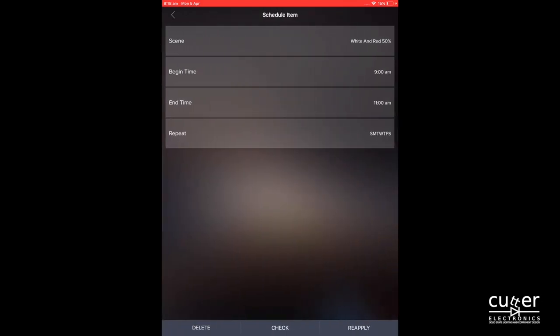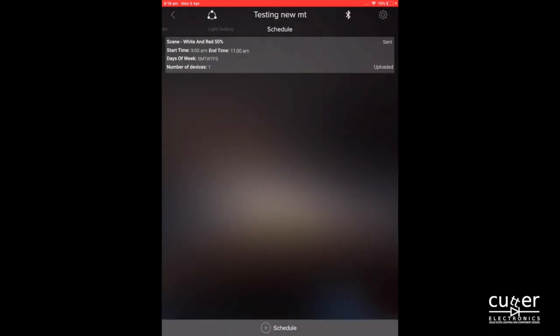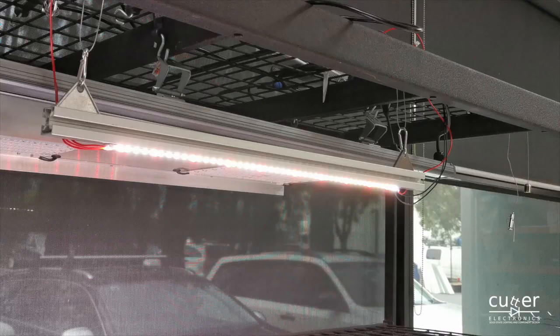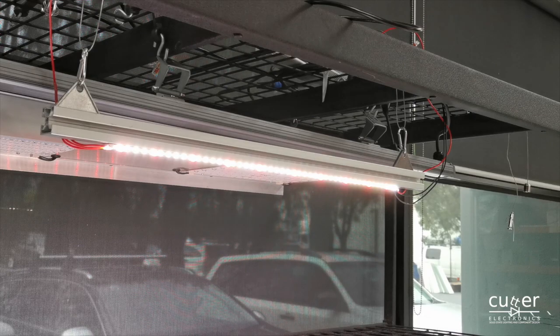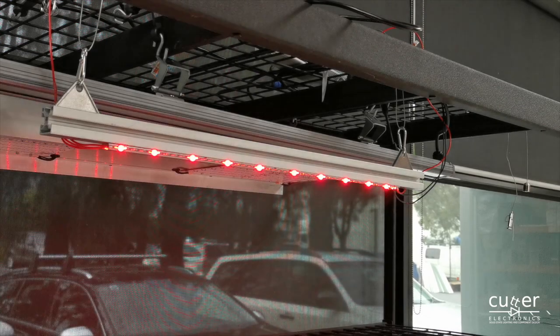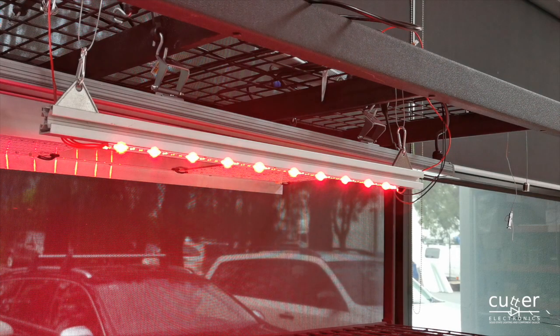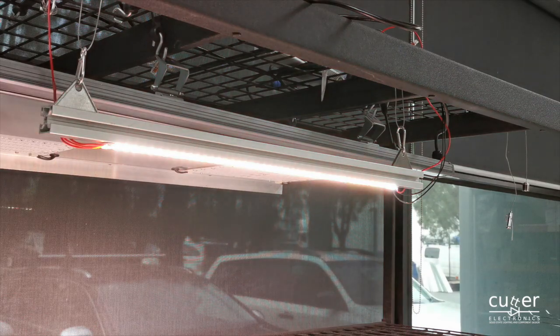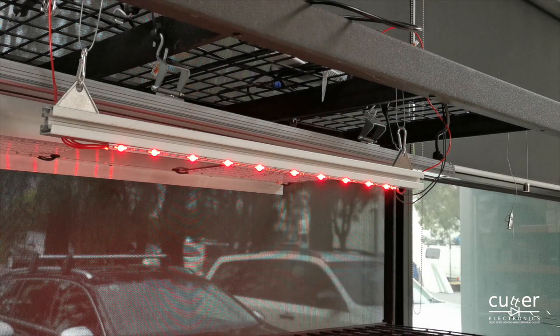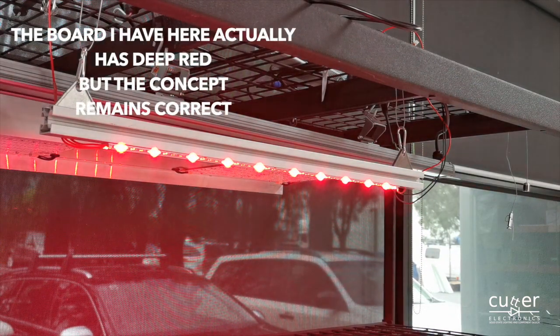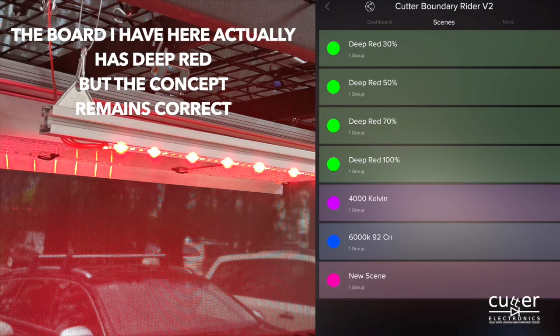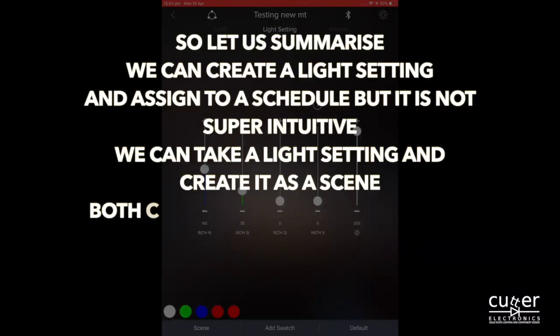For example, if I just wanted end of day for something like Emerson effect, I could have a channel of far red that comes on for 15 minutes. And let's say it increments in power settings of say 10, 30, 70 and 100%, and then reverses out of that over a 15-minute period. To do this, I just create 4 scenes, in this case on the far red channel, and at the 4 different power settings, and then load those 4 scenes into the scheduler.